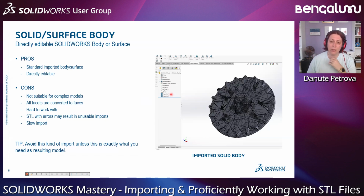As you can see here, it's solid feature, not mesh body, but the problem is that every single facet is turned to a face. So you have this structure, which is with tons of lines. You receive a really heavy model. And it's a bit rough because you have every facet as a face. Sometimes it's not smooth as it should be.